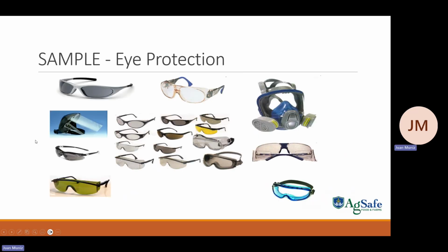And here are samples of the different types of eye protection. But again, you must check that they're ANSI approved. The way you see that is they have to have that number stamped on the frame on the inside somewhere, or on the lenses themselves. So you must look for that stamp to make sure that they truly do meet the brow and side protection along with the impact.